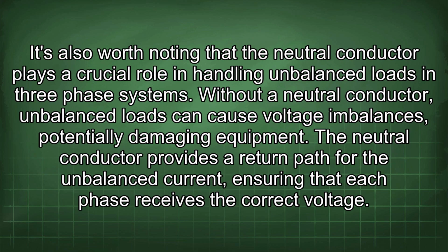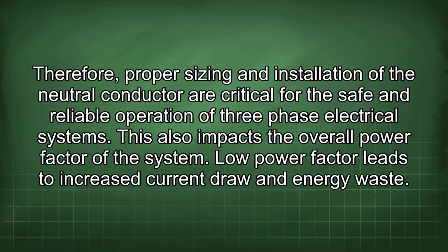It's also worth noting that the neutral conductor plays a crucial role in handling unbalanced loads in three-phase systems. Without a neutral conductor, unbalanced loads can cause voltage imbalances, potentially damaging equipment. The neutral conductor provides a return path for the unbalanced current, ensuring that each phase receives the correct voltage. Therefore, proper sizing and installation of the neutral conductor are critical for the safe and reliable operation of three-phase electrical systems. This also impacts the overall power factor of the system.